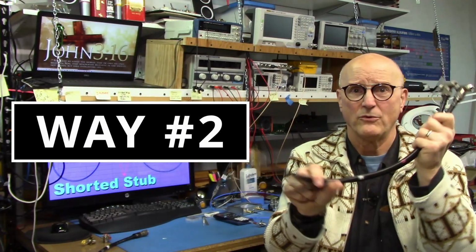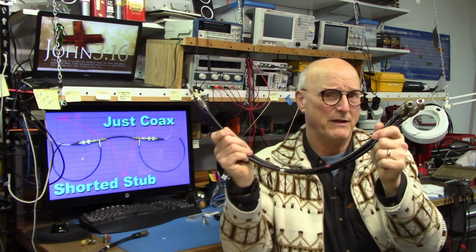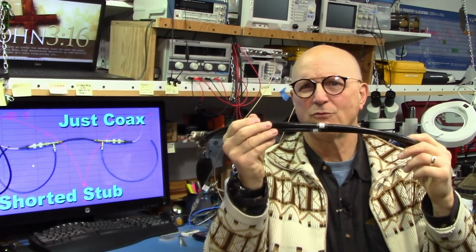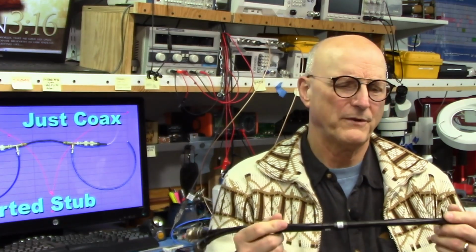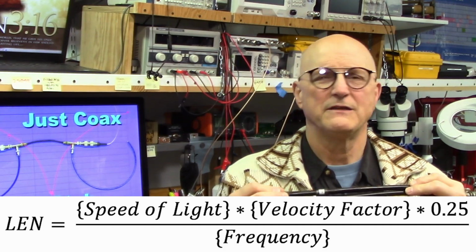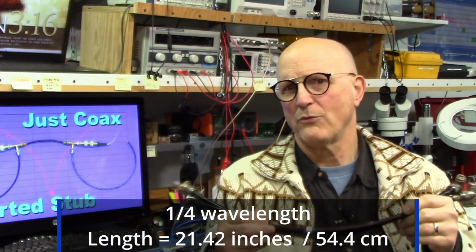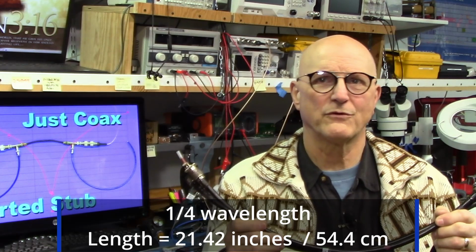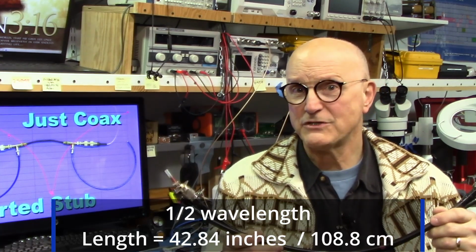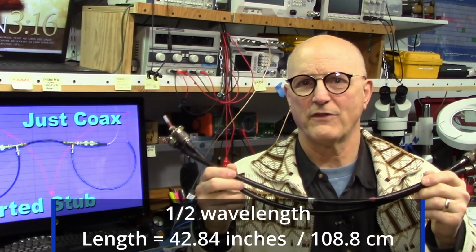Well, I dug around in my old cable box and found some cables that seemed to be long enough, but not too long. They need to be between 1/4 and 1/2 wavelengths long at the desired frequency. The frequency in question is 90.9 megahertz. The velocity factor of my coax is 0.66. So that means we calculate the appropriate length equals the speed of light in free space times the velocity factor times 0.25 divided by the frequency in question, which gives us 21.42 inches or 54.4 centimeters for 1/4 wavelength, and twice that, or 42.84 inches, or 108.8 centimeters for the half wavelength.